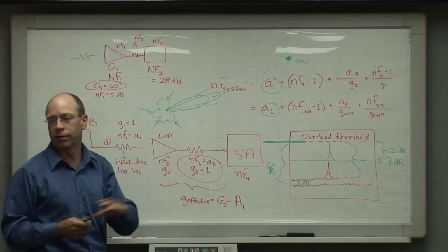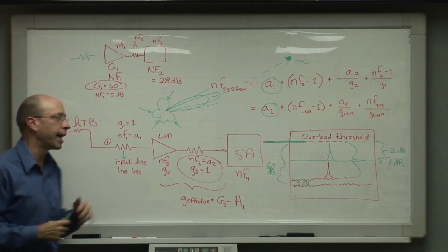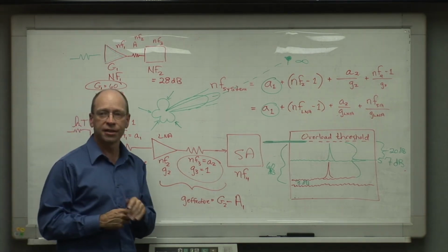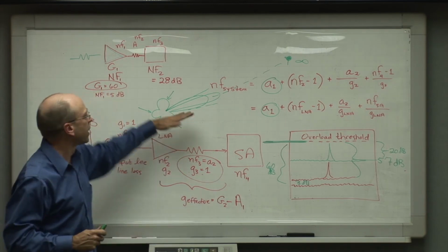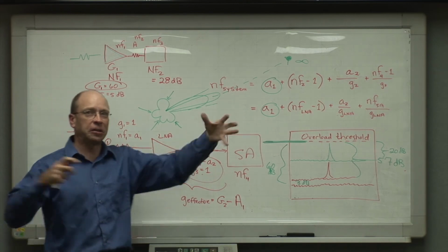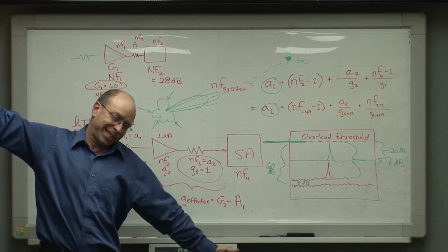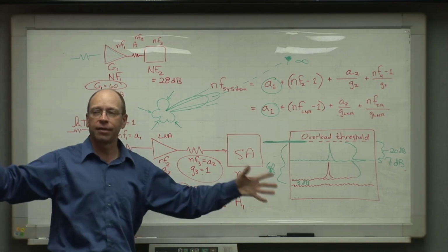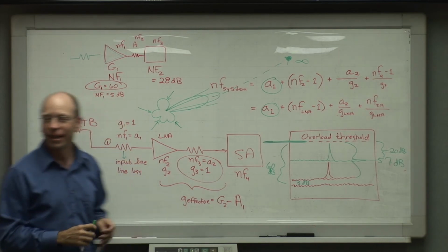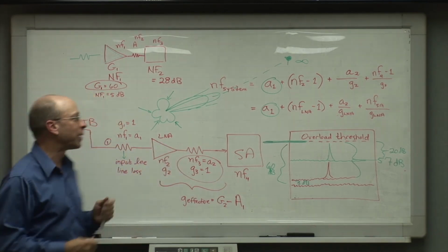And of course people do that for communication systems if they can set up a point-to-point link. There are a lot of advantages to that, although there is one little mechanical disadvantage. As antennas get bigger and heavier, they get harder to point, and they get more sensitive to vibration if there's a little bit of vibration in the mount. So you get this ultra huge, mega 3-meter dish antenna, and you find out that you can't hold it steady, and the signal's fluctuating up and down, and you back off to a smaller antenna. But that's just a practical limit, not a theoretical limit. If you're the US government, you just buy a bigger, heavier mount and keep going.